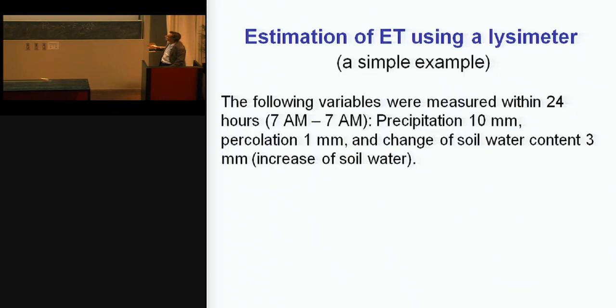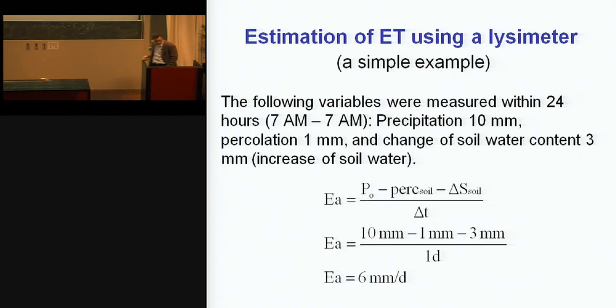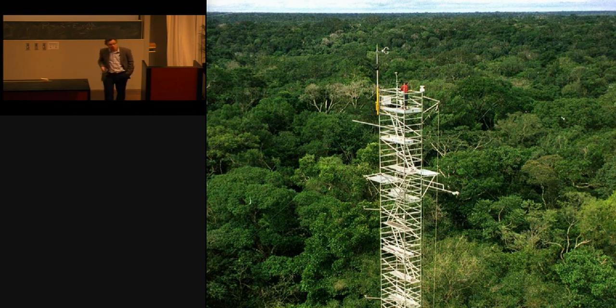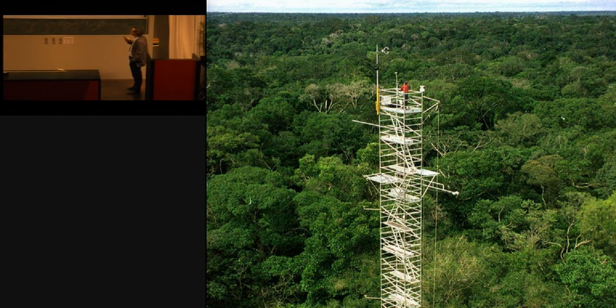Okay, this is the example again. You can study this little equation, I think, at home. Let's look at some pictures about measuring evaporation. I said the first thing to measure evaporation is with micrometeorological measurements, where we measure the rainfall. You see a rain gauge here. We also have rain gauges at different elevations. You have energy balance measurements at different elevations. And you also have wind speed measurements in three-dimensional space, showing the direction and the speed. And with this change of humidity and wind speed changes, you can really calculate the vertical fluxes of latent heat, and then you can calculate evaporation.